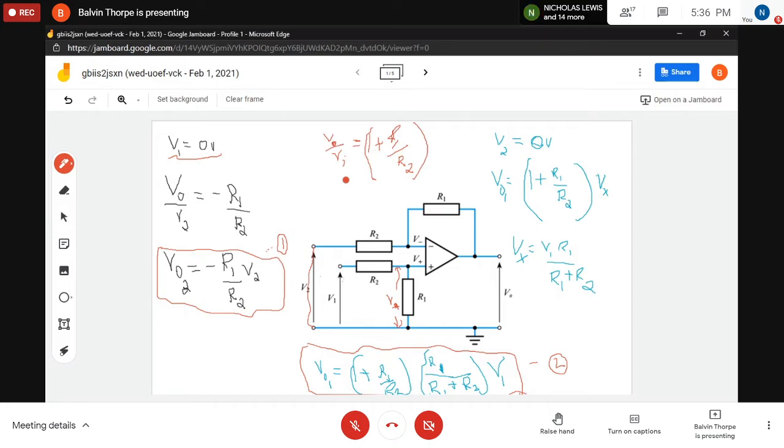Okay, so we're going to use the same concept for this very circuit. We want to know what the output voltage is when we apply voltage to V1. So when we apply the voltage at V1, that's going to cause current to flow through R1 and R2, and that is going to be divided between R1 and here. So not all of V1 will be going into the amplifier at the non-inverting input. Some is going to be dropping across R2, and whatever is developed across R1, you will agree with me that is what's going to go into the input of the non-inverting amplifier. Yes?